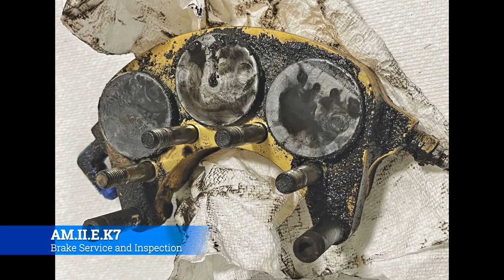Now, pulling the brakes, you're also going to be looking at seals. You're going to look for the housing and piston condition. You're looking for cracks and any sort of damage that may have occurred through just wear and tear, or pieces kicking up and cracking the housing, or scratching it or otherwise damaging it in some kind of adverse fashion.